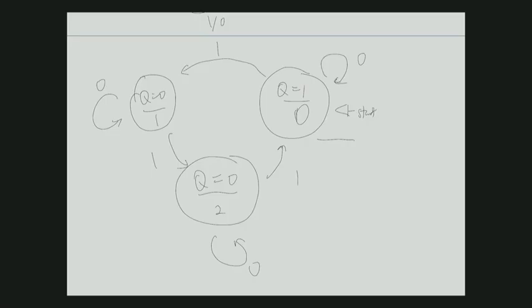One of them is called state encoding, a binary way of representing each state. With 3 states, you need 2 bits of information to represent it. So you really need 2 flip-flops to make the implementation happen. Which means these states, Q equals 0, Q equals 1, should also be represented by some 2-bit binary numbers. You can use any 3 binary designations as you like, 00, 01, 10, right? Doesn't really matter. Every state will be represented by 2 bits and eventually be implemented with 2 flip-flops.